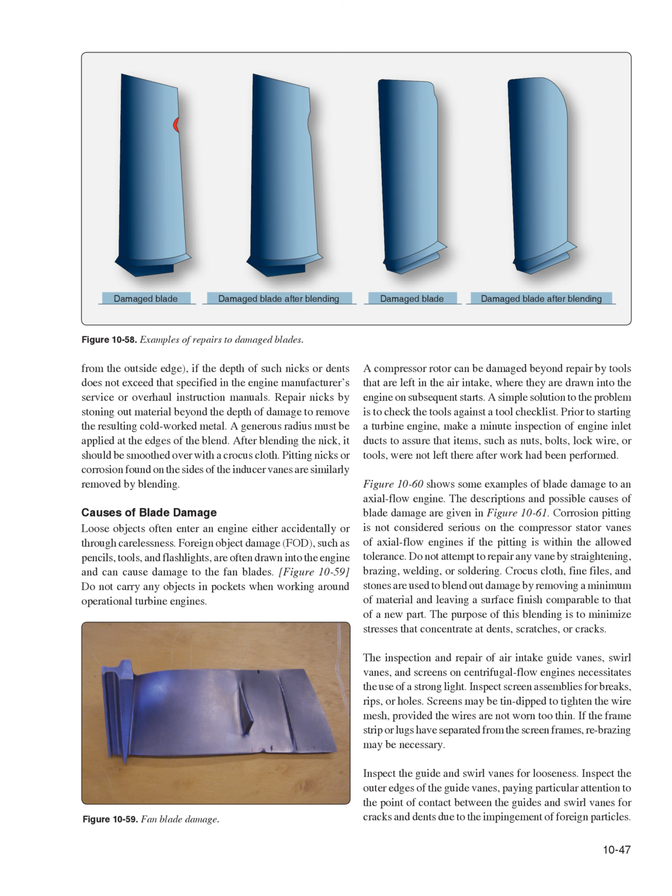Causes of blade damage: loose objects often enter an engine either accidentally or through carelessness. Foreign object damage, FOD, such as pencils, tools, and flashlights, are often drawn into the engine and can cause damage to the fan blades. Figure 1059: do not carry any objects in pockets when working around operational turbine engines. A compressor rotor can be damaged beyond repair by tools that are left in the air intake, where they are drawn into the engine on subsequent starts. A simple solution to the problem is to check the tools against a tool checklist.